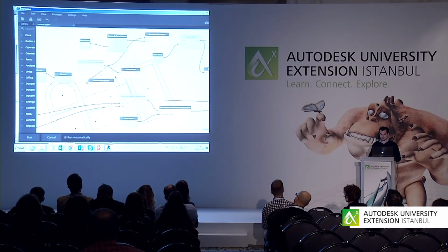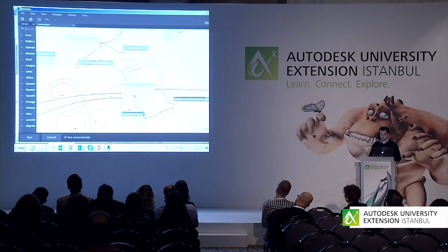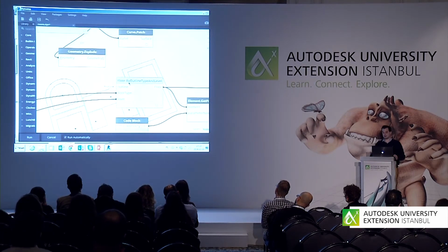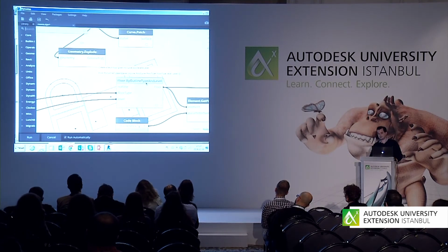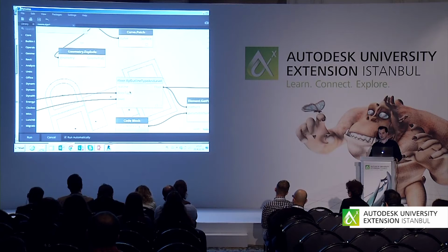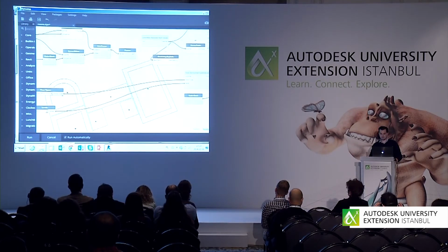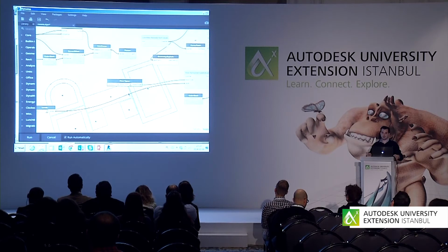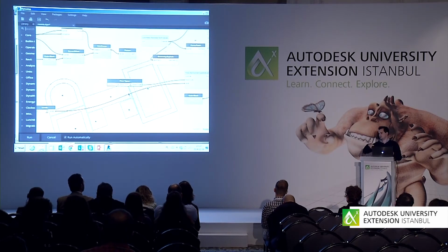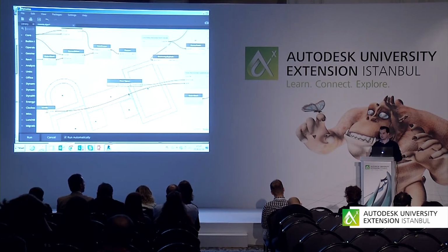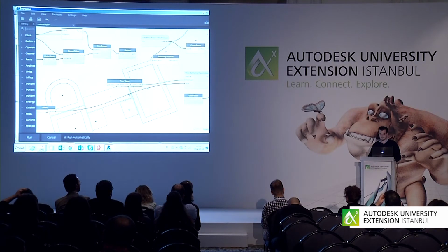What I will do now, as you can see, you can create a floor, okay? Floor by outline. And to create a floor with Dynamo, normally you create it by sketching its boundaries, right? But here you can help yourself a lot, especially if you want to control, for example, 100 rooms or, I don't know, 50 toilets, and you want to make sure that in every toilet you have the same material on the floor, okay?